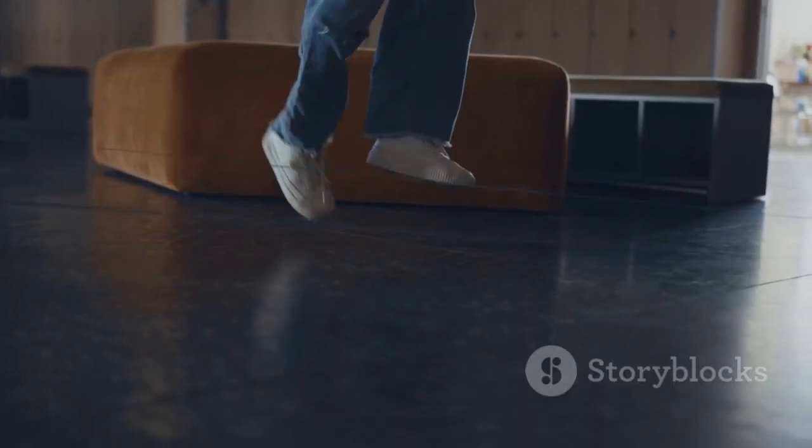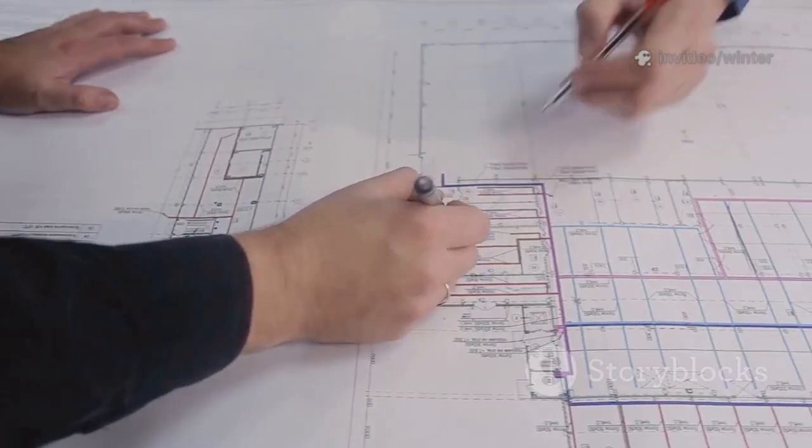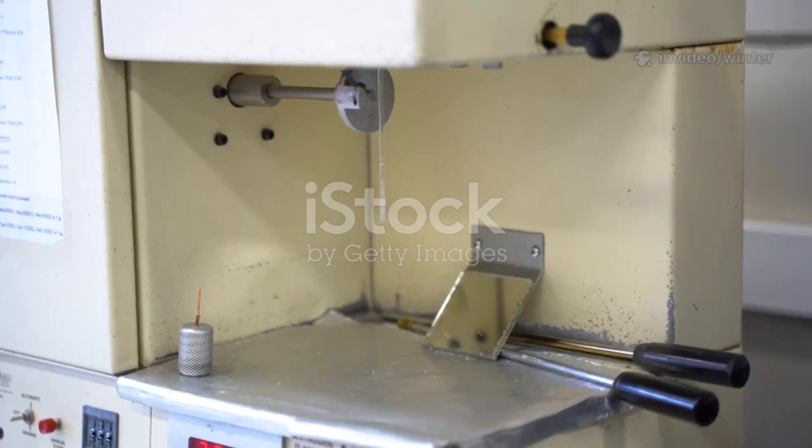Pull a 10 centimeter rubber band to 12 centimeters. The strain is 2 divided by 10, or 0.2. Strain has no units. It's a ratio or percentage of deformation. This lets engineers compare how different materials deform no matter their size.